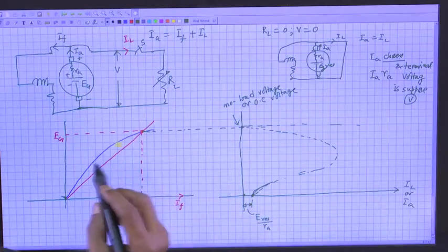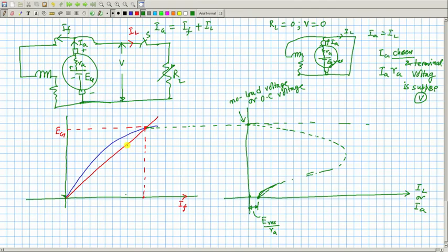That is, I will write here. So, I have chosen a terminal voltage, suppose this is the terminal voltage. This part is also very interesting. So choose a V. If you have chosen V, I will say field current is this much. How much is the generated voltage? Assuming speed remaining same, generated voltage must be this much. From OCC I can read.